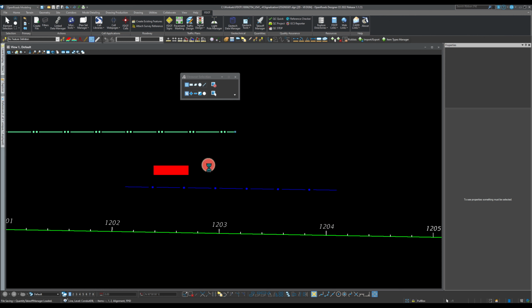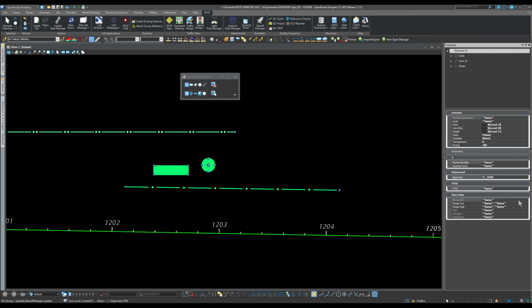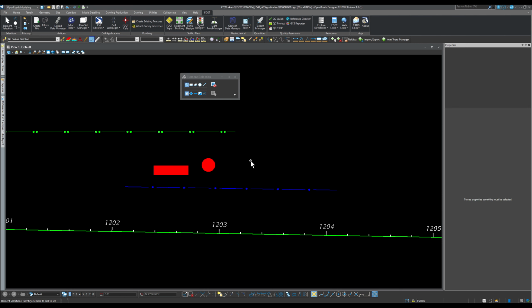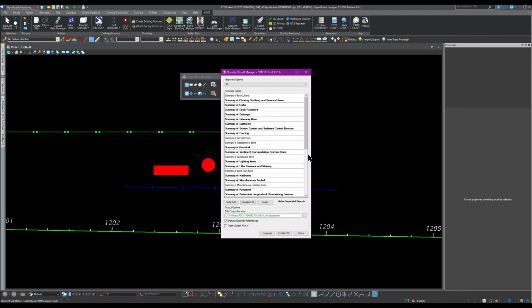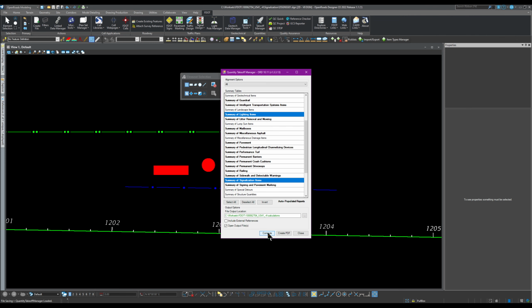Let's make all of them actually have the same FPID. Since I selected all of them, I'm just gonna go here and make all of them the same project number. Make sure it's saved, and now let's do Takeoff Manager. So let's run it, right? Let's run signalization. And also let me run lighting too, because I want you to see that. Compute.